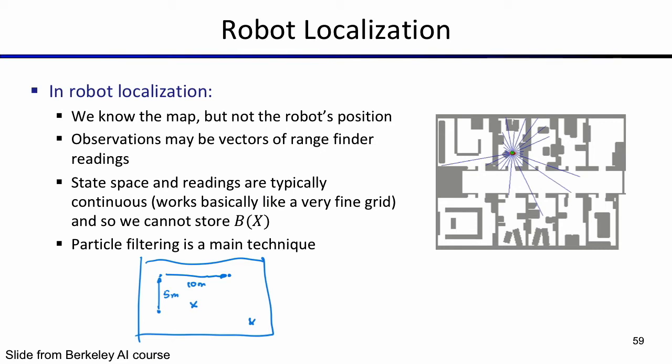The problem with this solution is that even though the encoders are very precise and they tell you how much the wheel has turned, the floor might be slightly slippery, or the robot can touch an obstacle and stay stuck somewhere, and you think that the robot is moving, but actually it's not. The wheel will turn, but the robot will not move. Or it will move, but much less than you expect.